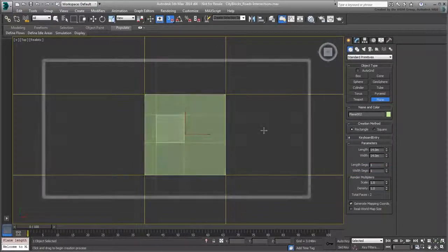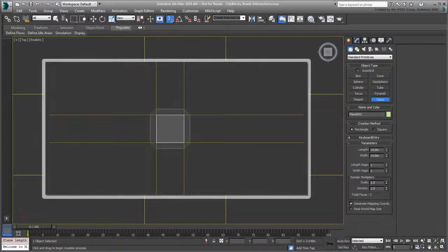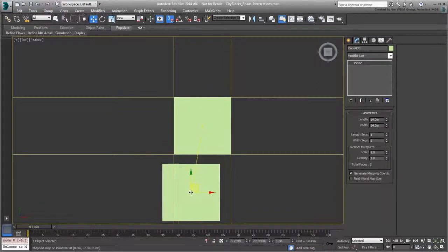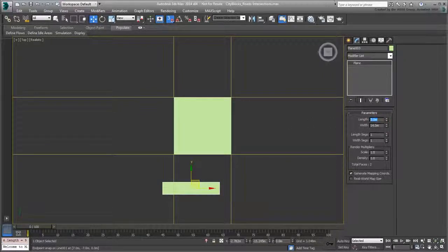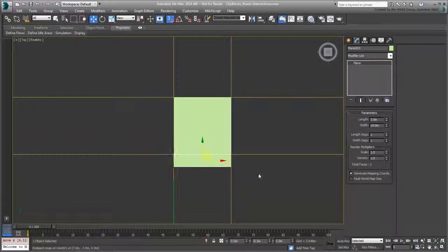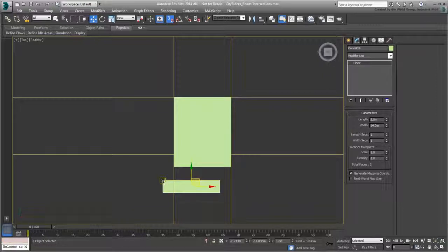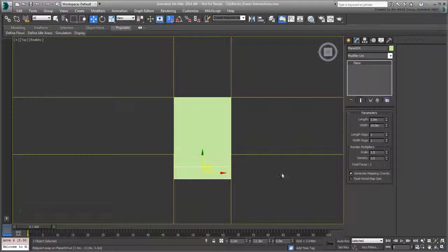As explained earlier, you need to expand this to favor the curved or chamfered lots and sidewalks. Copy the intersection lower and change the length to 3 meters. In this case, 3 meters represent the chamfer value you will use for the sidewalks later. Using endpoint snaps, relocate that strip of asphalt right below the intersection. Make a copy of that strip of road below the current one. This one represents the pedestrian crossing and will be mapped differently.